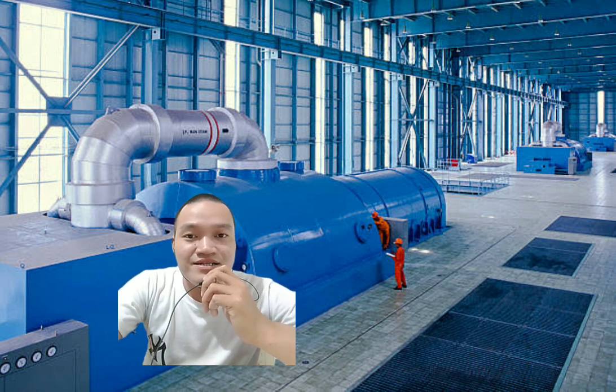So the ahead steam is shut off by the use of an emergency trip. The astern valve is partly opened to gradually increase the steam. So the turbine can thus be brought quickly to a stop condition and can be operated astern if required.